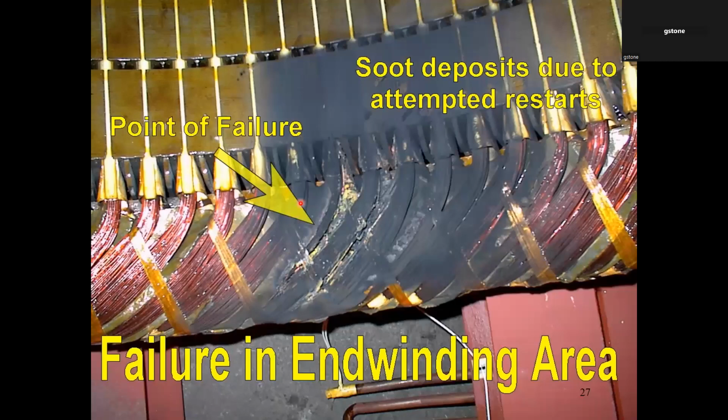Okay, so here's just an example of an industrial motor where there were partial discharges occurring between the turns caused by inverters. And of course, it failed. The turn-to-turn insulation failed. There was a lot of melted copper around there when we did the forensic analysis, and that's a sure sign of shorted turns. And all the soot and stuff is caused by the fact that, of course, operators say, well, it didn't start. Let's try it again. Let's try it again. And you get a lot of collateral damage that makes forensic investigations a little bit more of a challenge.